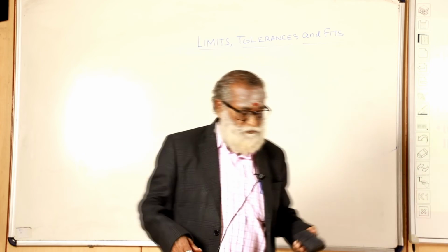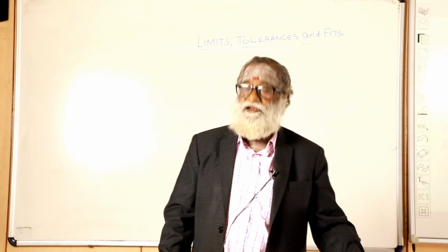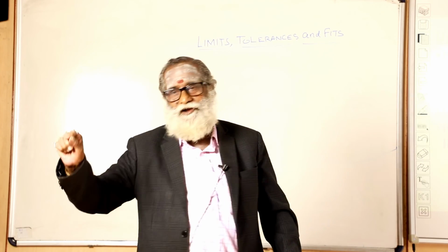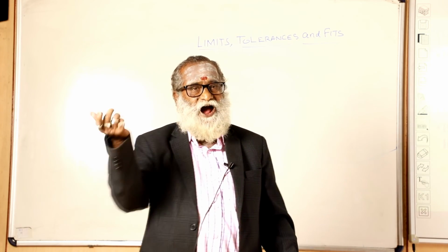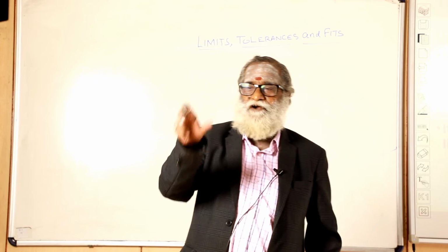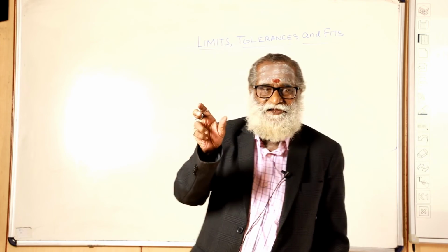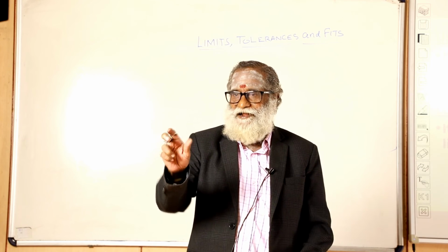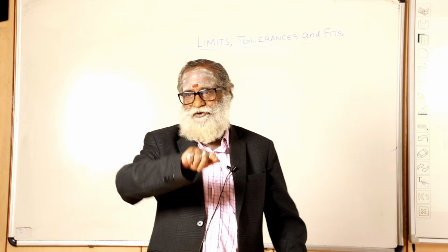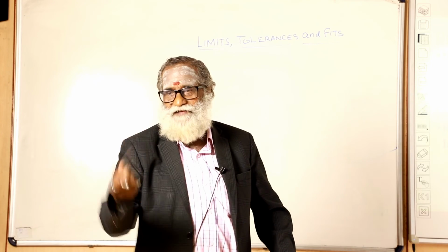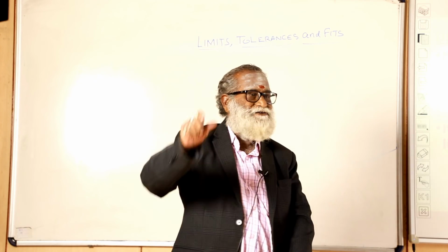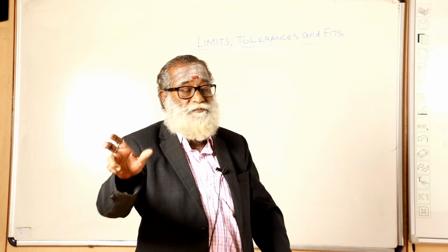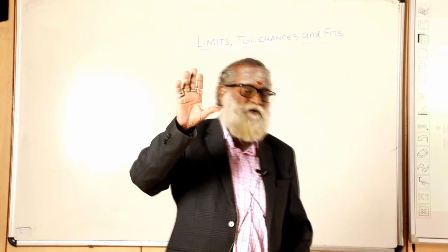Today we have seen limits, tolerance and fits. Generally, we used to say in the workshop limits, fits and tolerance. It is not like that. It should be limits, tolerance, and next only fits. Because after the tolerance, you have to decide the type of fit, whether it is a push fit, force fit, running fit or sliding fit. Fit does not come before that. So, after the limit, tolerance and deviation, you decide which type of fit is suitable for that particular component in the interchangeability of mating parts. That is more important.